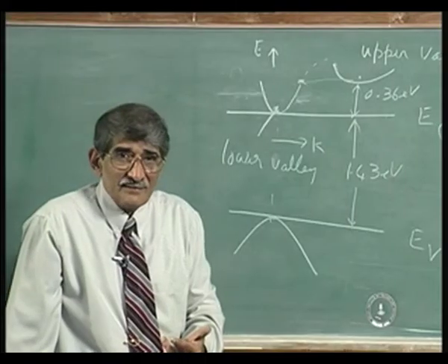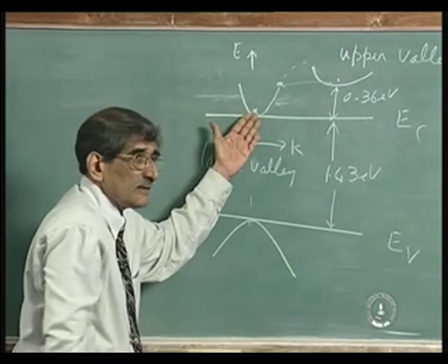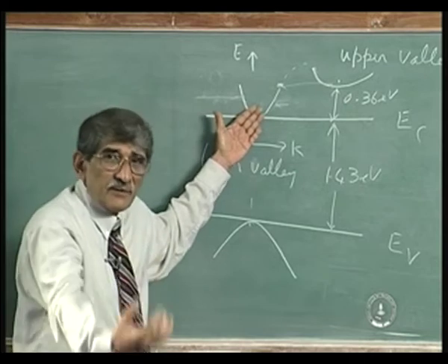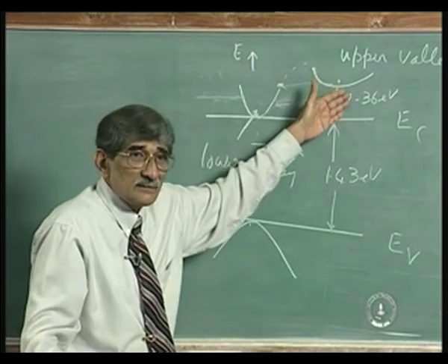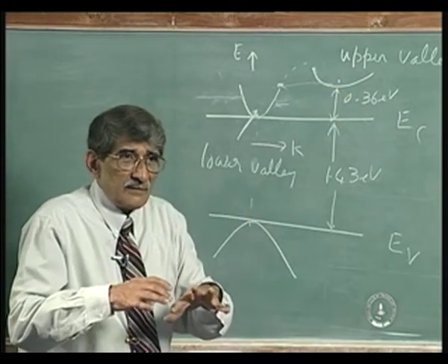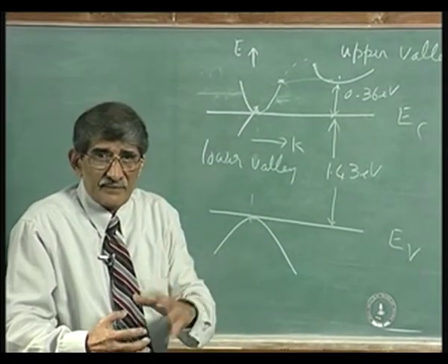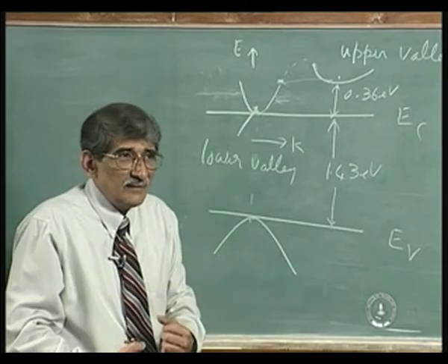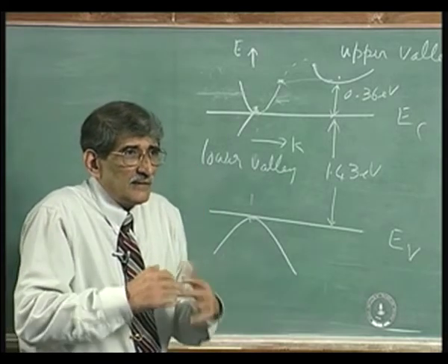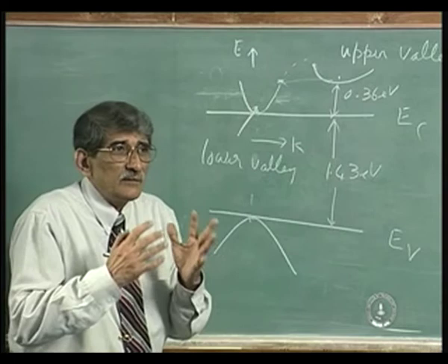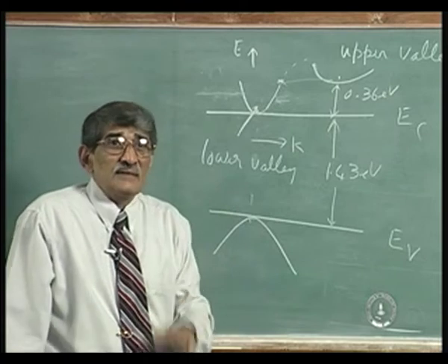In silicon, what is the difference? So, as you increase the field, electron velocity goes on increasing because it absorbs energy, but beyond a certain energy, the electrons get transferred onto this upper valley. In fact, what you can say physically is the mode of its transport changes slightly, the way it moves is slightly different. Physically, you can just visualize it this way. I do not see it written in black and white anywhere, but my own thinking is, in between silicon and gallium arsenide, what is the difference?